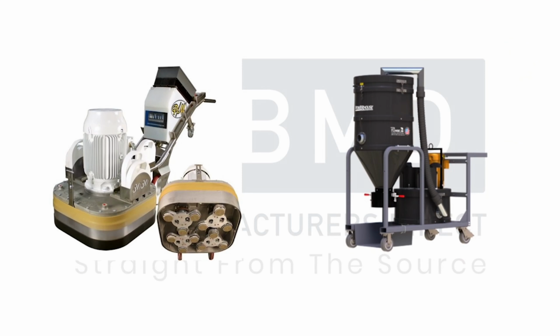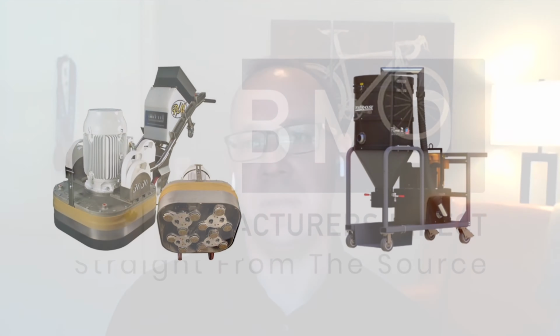Again, if we're looking at a Ruwac vacuum system paired up with a prep master grinder, for example, depending on the platform size, we want to determine what we think is going to be the appropriate amount of CFM and appropriate amount of lift. We want to think about lift being what's getting that product off of the floor itself, and the CFM is what's helping move it or convey that material through the hose.